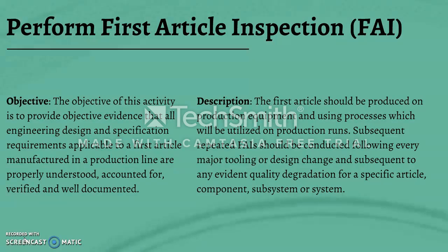Subsequent repeated first article inspections should be conducted following every major tooling or design change and subsequent to any evident quality degradation for a specific article, component, subsystem, or system.